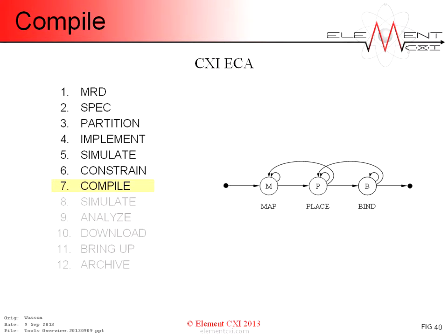Targeting has already occurred when implementation is done using target-specific libraries. Because of the full interconnect architecture, no iterations are required for binding or placement, which means neither rip-up and retry placement nor context element remapping are needed. This greatly reduces compilation time from hours for FPGAs to seconds for an ECA.